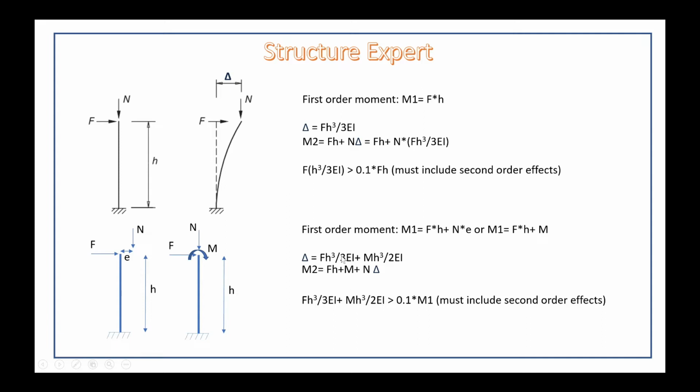And it is similar when you apply moment at the top. You can use the formula, and the verification is the same. If over 10% of the first moment, you might include the second order effect.